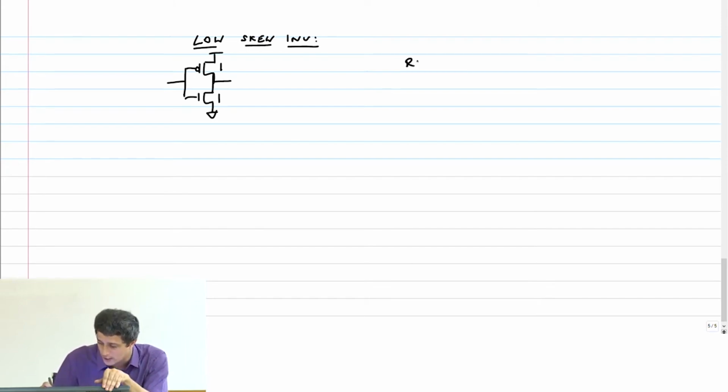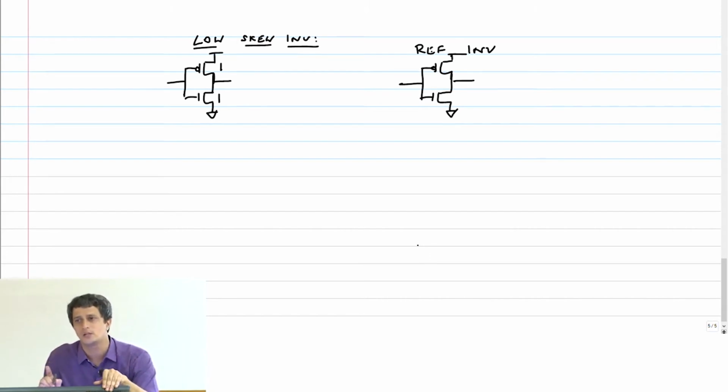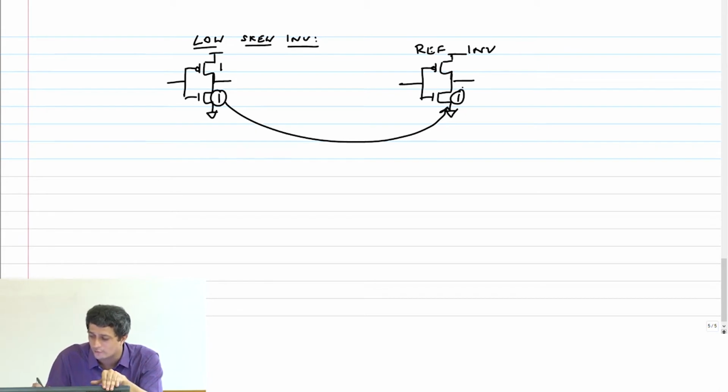We first constructed the reference inverter. And how did we construct that? Let's say I wanted to do it for pull down. I needed to construct the reference inverter such that the NMOS transistor had the same drive strength. So I said this you can put here, right? And therefore this will give you 2. And then we calculated the logical effort, right? But this is equivalent to saying that the current to this guy is actually I.